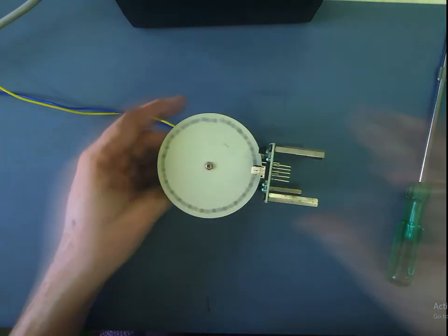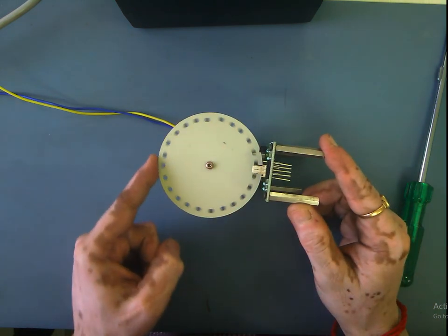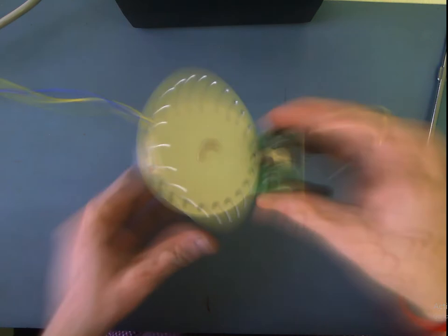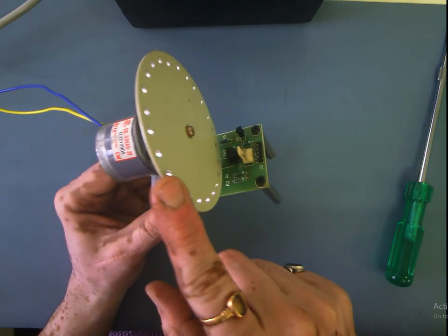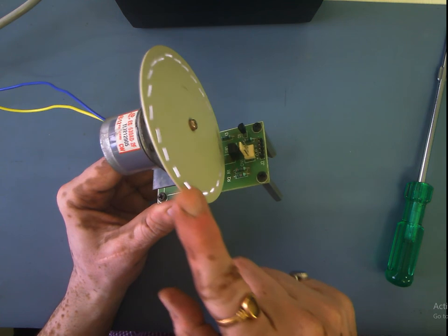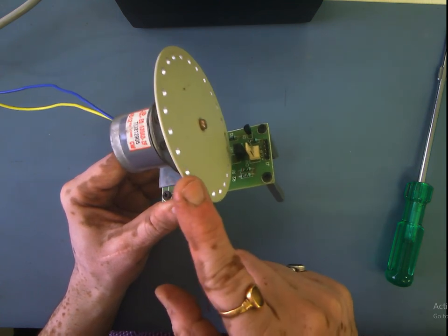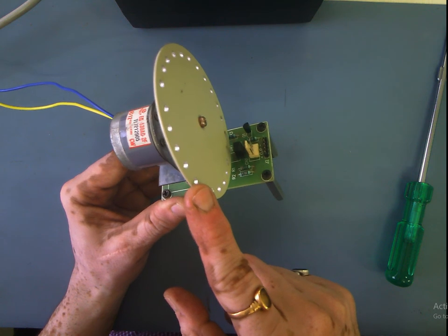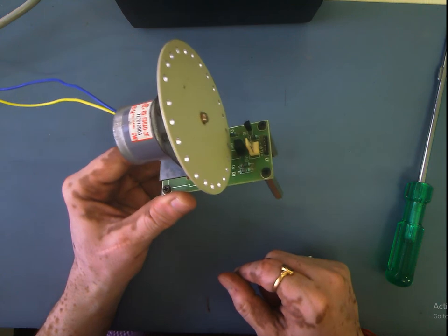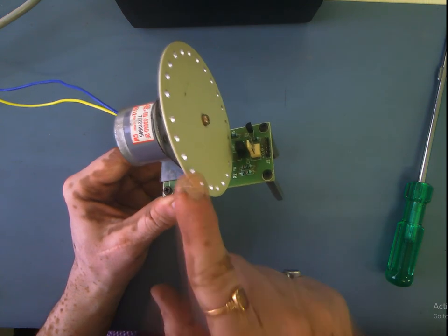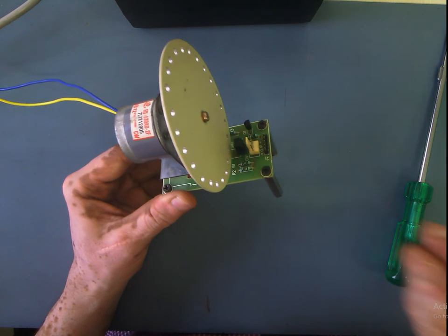It is connected, and now I will just rotate it slowly by hand. Now you see, when it is rotating like this, what is actually happening? This is rotating in between the IR diode and the phototransistor. When there is a hole, the phototransistor will be getting the signal from the diode. And when there is no hole, that is, there is an obstacle, the phototransistor will be getting no signal.